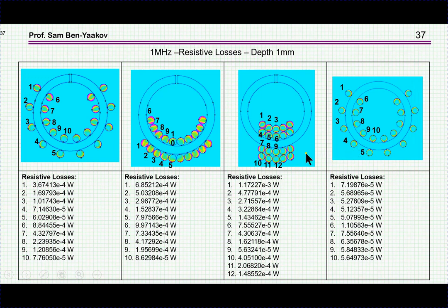Now also, of course, I'm showing here a large diameter in order to sort of emphasize the effects of both the skin and proximity effect. In order to reduce the losses, you'll have to use a diameter which is much, much smaller. That is, the skin depth is perhaps an underestimation of how small the diameter should be. In fact, the diameter should be much smaller than twice the skin depth because of the proximity effect that we have in here.